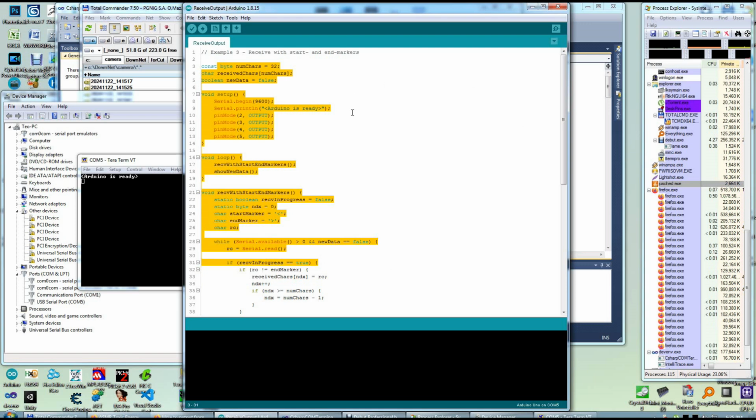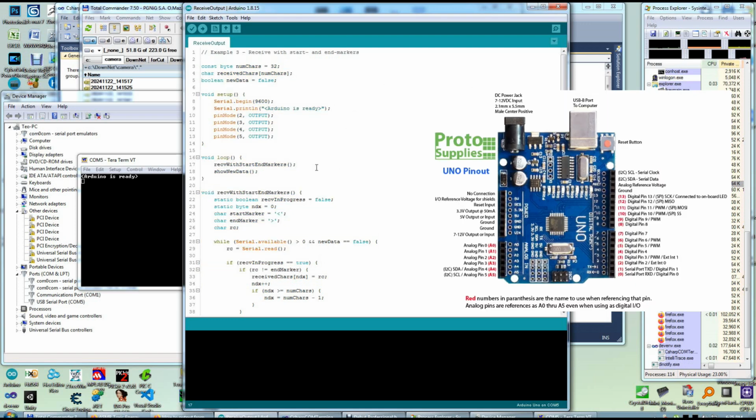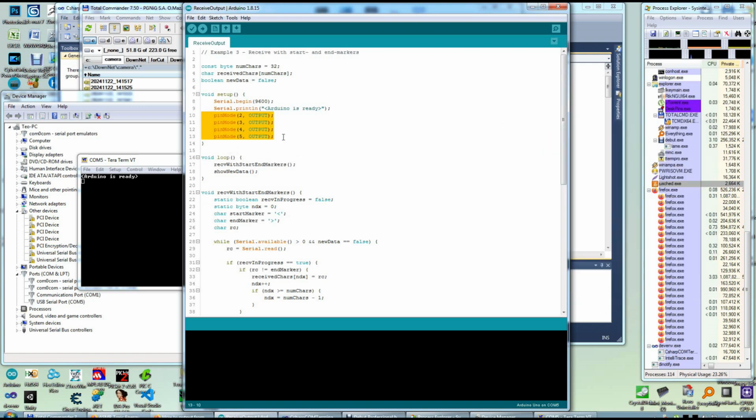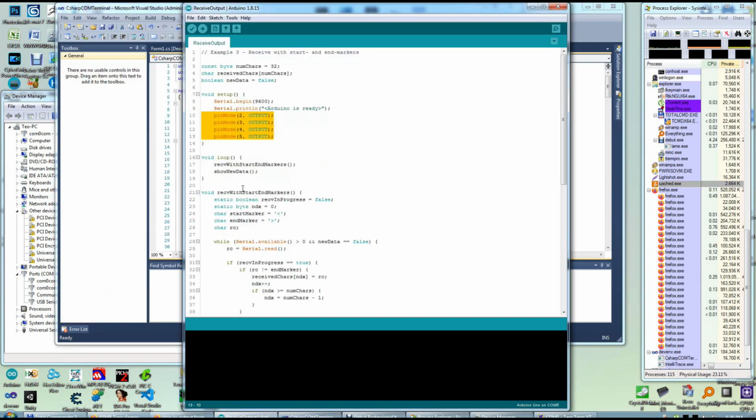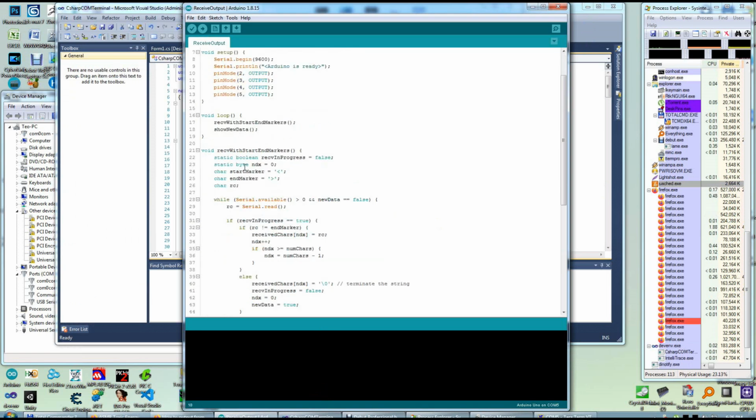All this code that you are seeing here is programmed into my Atmel 328, into my Arduino Uno. This code is inside it, and I don't have to code anything after I write this code into it. You upload it once and you leave it there, and that's it. This code is practically interfacing between my computer, my C# program, and the LEDs, these 4 LEDs. So this program sits between these 2 elements. These pin modes are set as outputs in the setup.